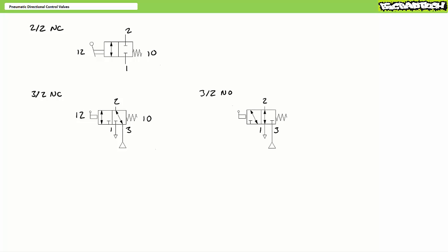In contrast, a lever-operated normally open 3x2 valve might say 1 2 on the spring and 1 0 on the lever, meaning the offset spring passes 1 to 2 in the normally open deactivated state and the lever blocks 1. In keeping with this standard, the actuators on a push-button operated 5x2 directional control valve might have the following numbering: 1 2 on the spring offset and 1 4 on the lever, meaning the offset spring passes 1 to 2 in the deactivated state and the lever passes 1 to 4 in the activated state.